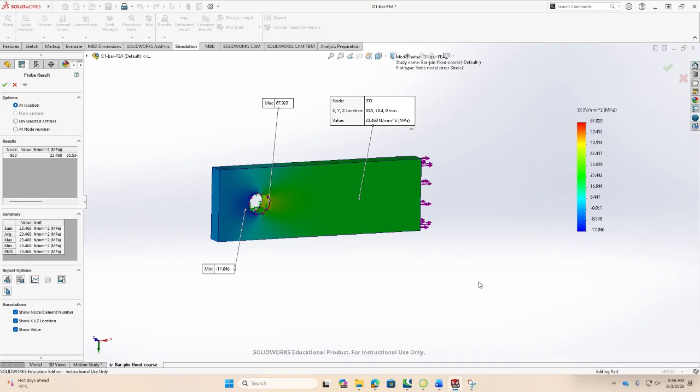It will be very difficult for me to even go further down in the mesh. You can try with different meshes to see if the values converge, and I'm quite sure that the values will actually now kind of converge around this number. So the main problem here is whether there is a better way of applying the boundary condition or not, even with the same mesh. So today I'm going to demonstrate, because I don't have the time to now run it with several meshes, but I can still show you the other way of applying the boundary condition.